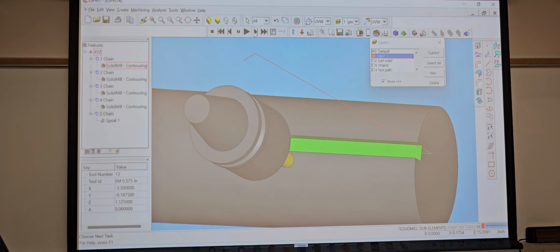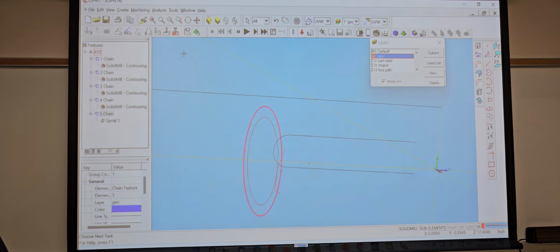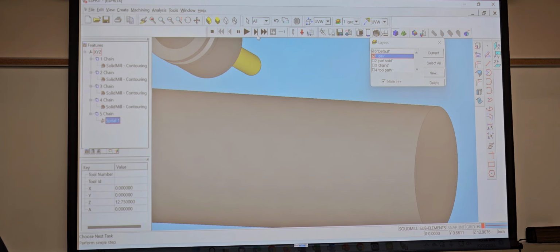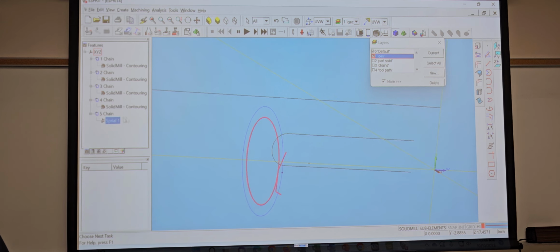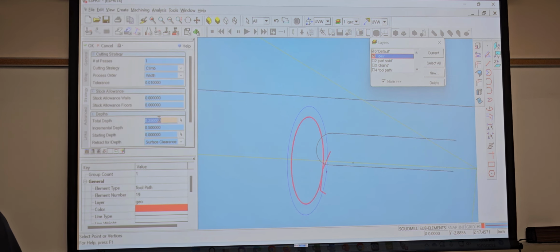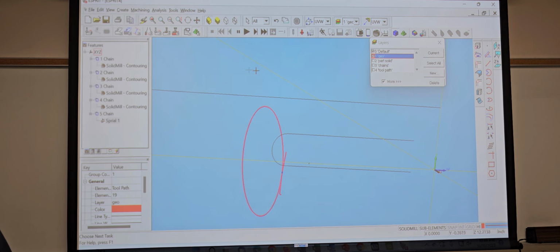And that distance doesn't look right, because it looks like it's gonna cut into your grooves, or your slots. Oh, maybe not. That's the angle you had a while ago. That looked like right there was gonna cut it off. Down, over the down, there we go. Alright, leave the depth at 0 because the chain is already down there. So leave that at 0.